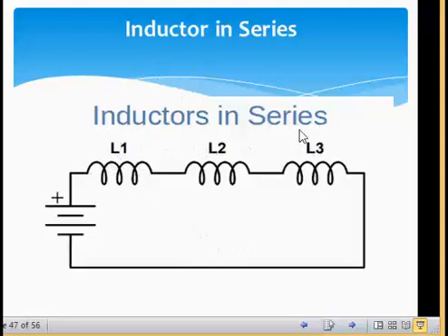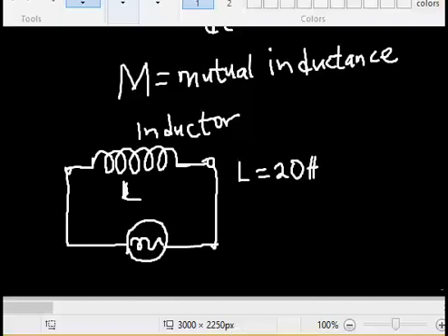So now this is inductors in series. Inductors connected in series, you can evaluate the total inductance. To evaluate the total inductance, you just add up the individual inductors.